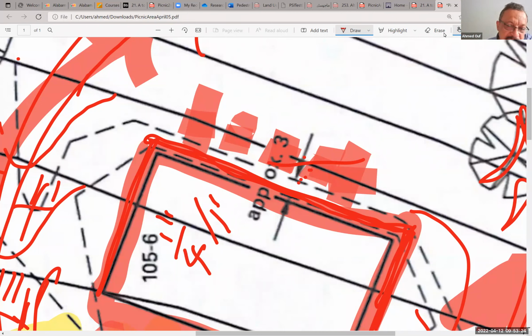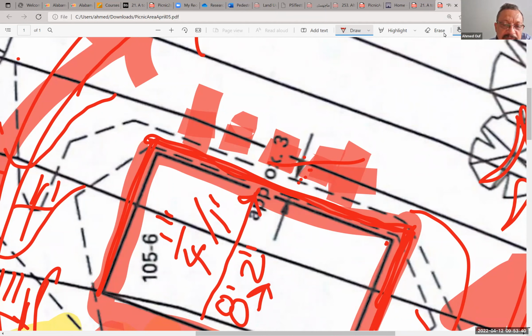So if this is like 8 feet or something, the whole slope between this point and that point is 2 inches. If it is 8 feet, I will have only a drop of 2 inches for the whole thing. So you won't really feel it. But a quarter of an inch in every foot is kind of an average thing you can use. You can do even less than this, 1/8, but it doesn't make sure that you lose all the water from collection. Anyway,